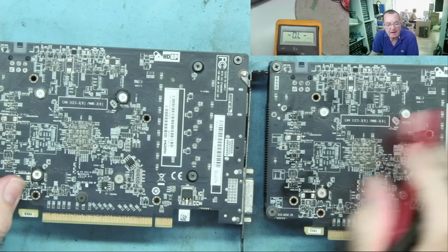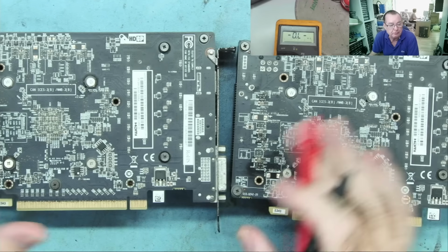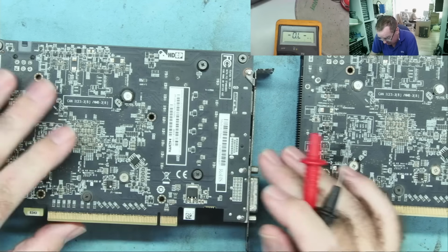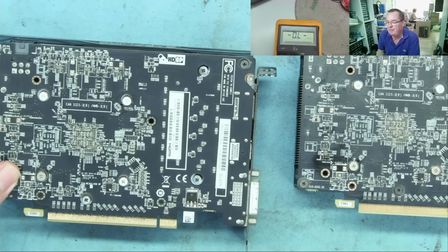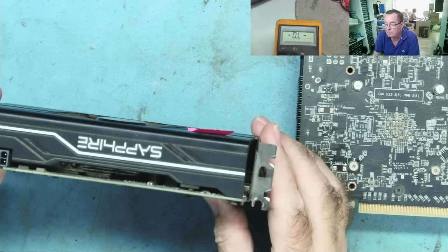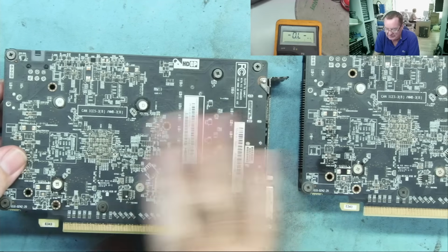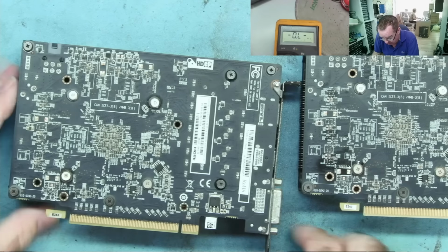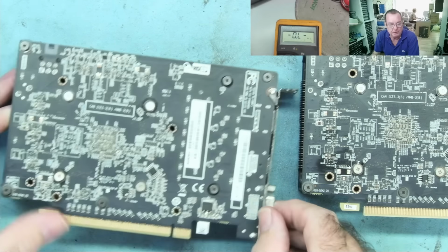So there's a fairly simple process we can go through with any graphics card really. Just follow the dotted line basically, and this will give us a very good indication of what's happening. So first thing would be to do a visual inspection. Although we can have damage on either side of the board, if we're talking about physical damage, it's much more likely to be on this side because there's nothing to stop components getting broken off the board. If we have damage on the other side, it's much more likely to be something burnt.